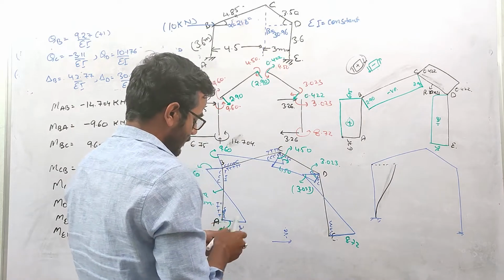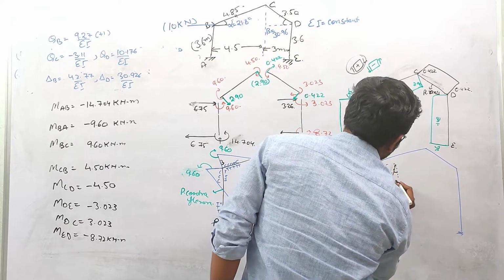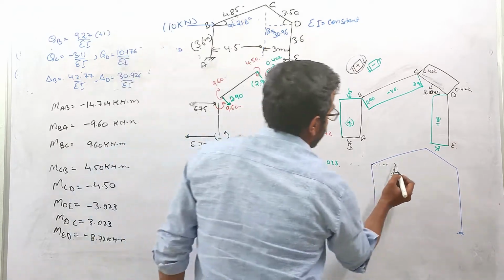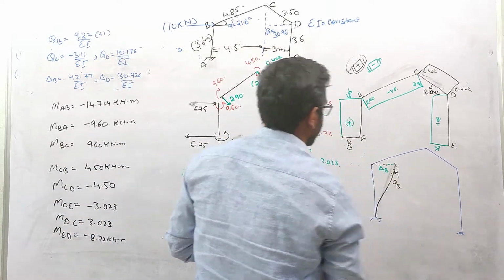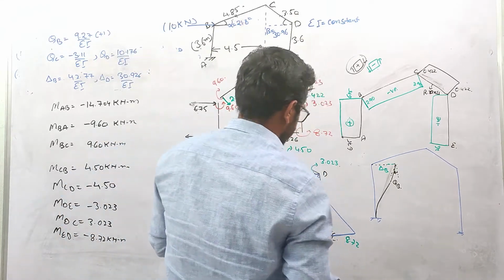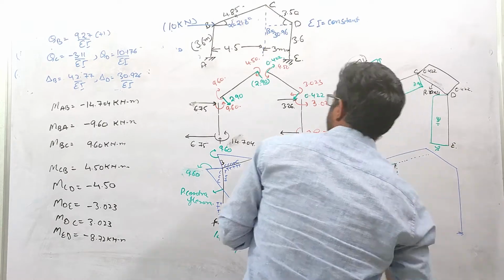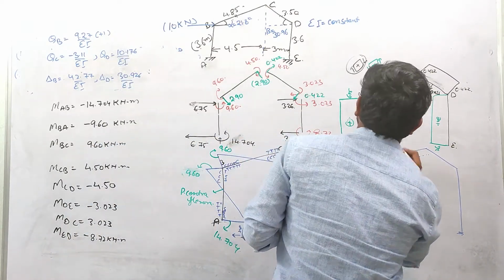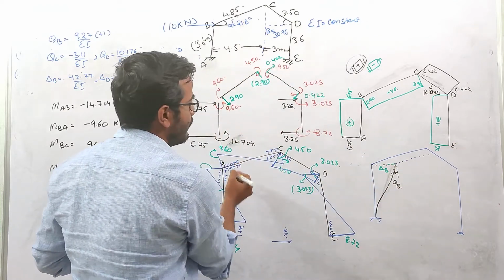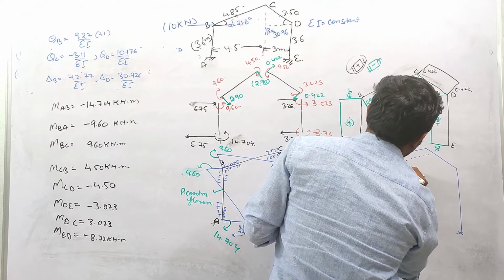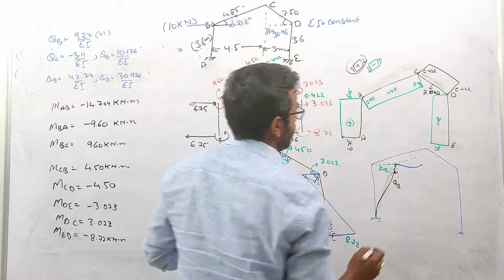Okay, so you can see that this is basically tangent, this is reference line, and this is basically the tangent. So this is theta B value. Okay, and this is anti-clockwise, this is clockwise basically. This is delta B, which we have already calculated. Okay, now let us suppose if this is our reference line and theta B is clockwise, anti-clockwise over here, and you can see that through the bending moment diagram, this portion, this upper face is in compression and the lower face is in tension, so it will bend like this. Okay, and somewhere here at the point of contraflexion we will have some point of inflection.